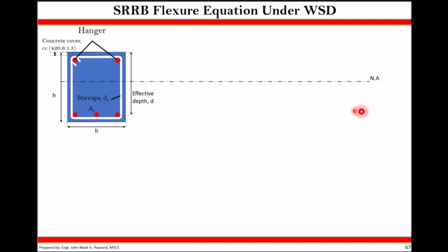We draw your neutral axis in order for us to establish and draw the transformed section for a cracked section. As we all know, there will be concrete at the top and reinforcement at the bottom, and we convert that reinforcement by multiplying it by the modular ratio n. nAs would now be the area of my steel at the bottom of the neutral axis.